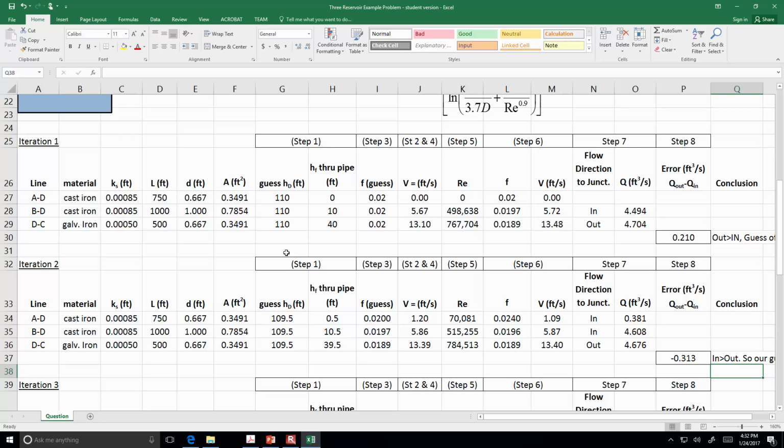It seemed like, in a handful of cases, there were slight differences in velocities or F values, and I don't know if those are maybe in the way that your computer is estimating pi, or if you typed in 3.14 instead of the pi function. But for small, like less than 1% differences that may arise at this point, I'm not too concerned yet. It's when we get to the final iteration, the flow rates and the F values, hopefully will tighten up and match my spreadsheet versus yours.